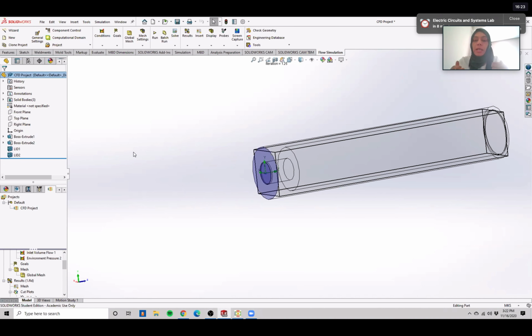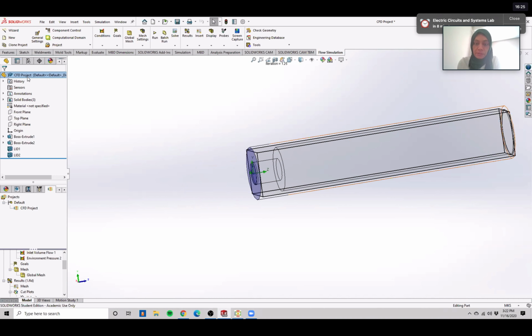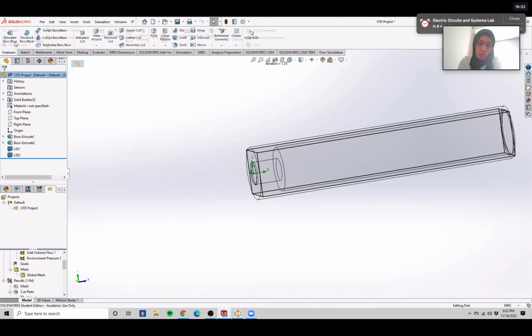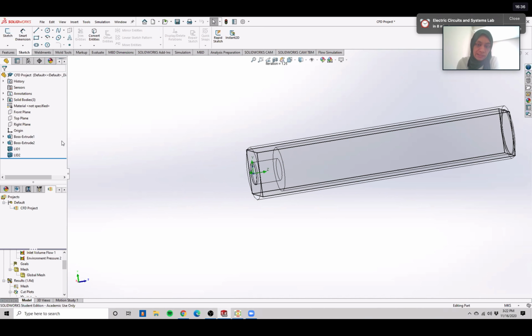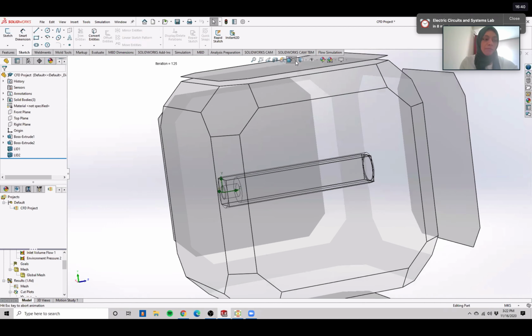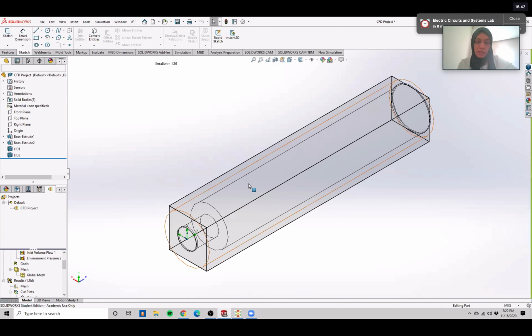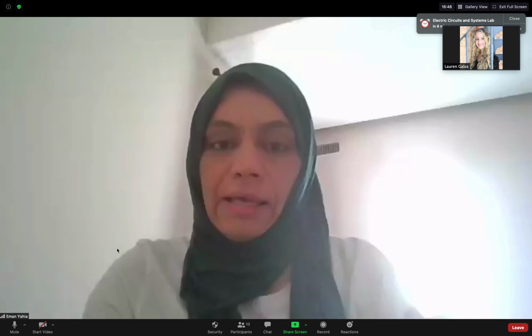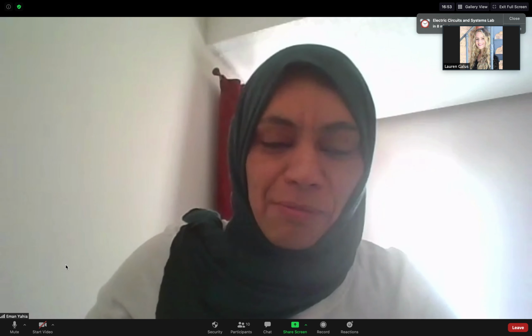It's important to make the first part so short because you want to let the flow go to fully developed. If you make this part at the beginning long, that will cause some problems finding the pressure at the end. So the setting that he did, this shape is so good. I think you will get a very good result with this shape. Okay, thank you very much. So Lauren, if you set your model correctly, then I think you will not have any problem setting the boundary condition.